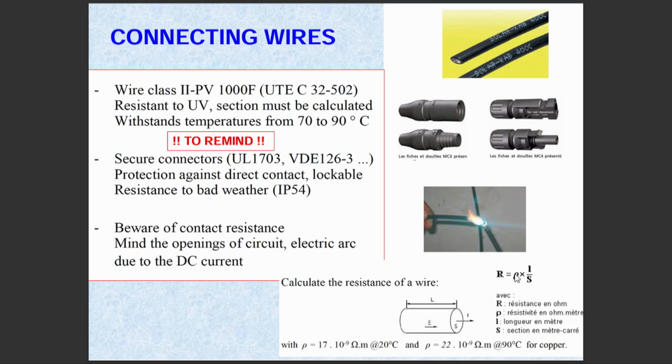This cable also to have a specific envelope, okay. Specific because usually these installations are outside, or the cable are outside, so they are submitted to UV, okay, and the UV is very strong for attacking the polymer, so this cable has to have UV protection, especially because such PV central could have a lifetime around 20 to 25 years, okay?